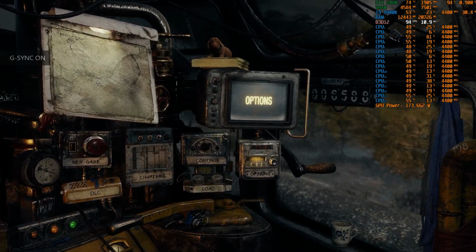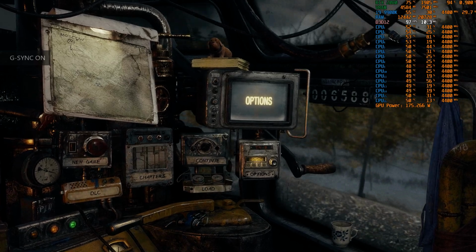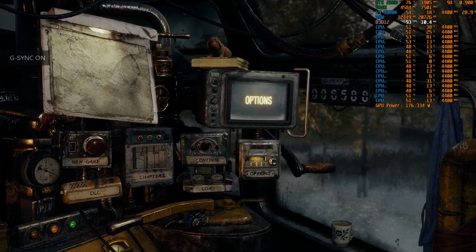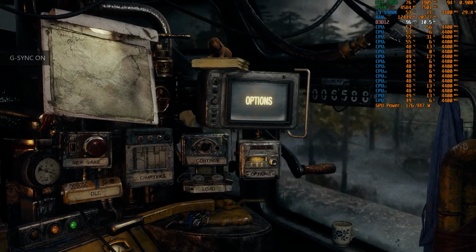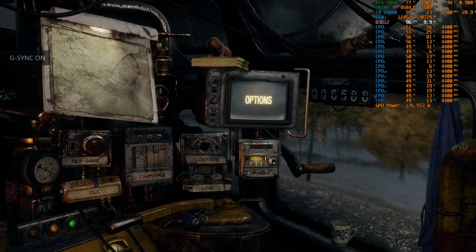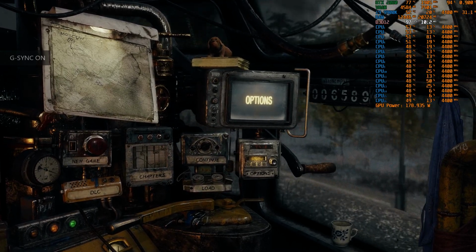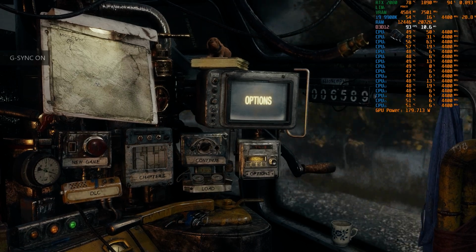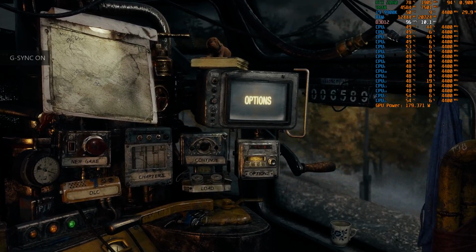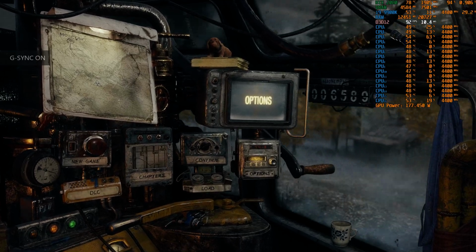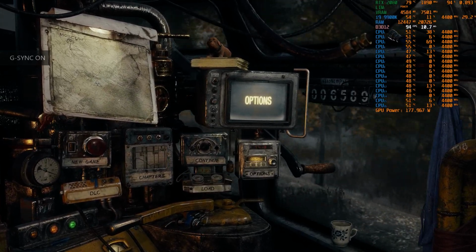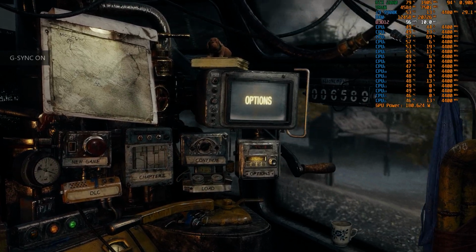So this is how you play and this is how you make it, and this video is getting really long by now, but anyway, I hope you enjoyed this video and I hope it was really helpful and you understand how you overclock and undervolt at the same time, and how you can create your custom curve, voltage-frequency curve, and how you can tame the temperatures in this machine. And this doesn't apply only to the Alienware, this actually applies to every PC out there. So even a desktop that's air cooled or even water cooled, if you want to keep the thermals in check or whatever. But basically this is how you overclock and undervolt.